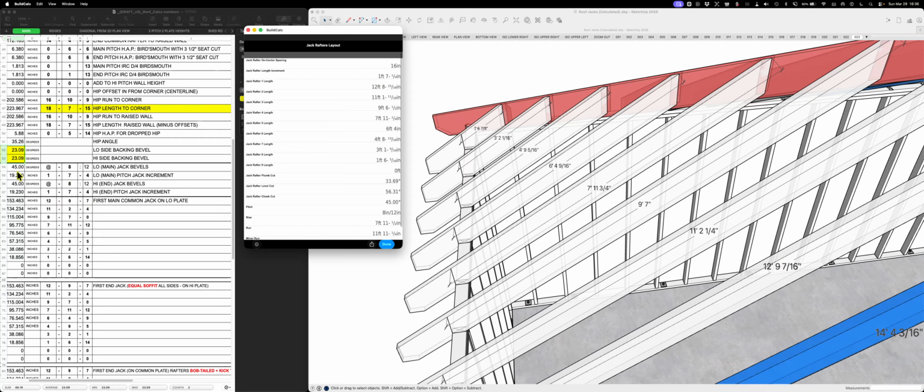And the only reason this becomes an issue at all, if you want to step back, is when you're a lowly little framer, you've been framing for a couple months, and you're putting plywood down on the roof. As you're coming across, you notice that the 4-foot edge of your plywood and whatever jack you're about to land on don't line up. It's like the jacks are crooked, because you know that 99% of the time the plywood comes from the factory square.